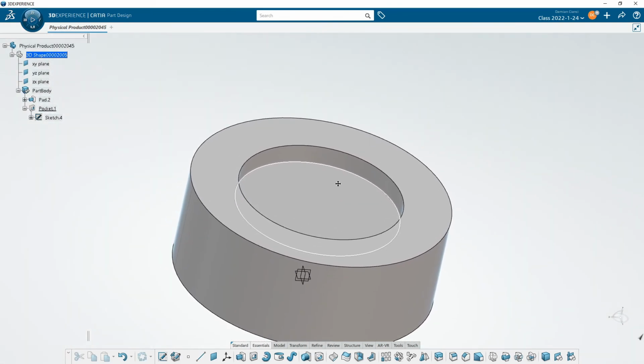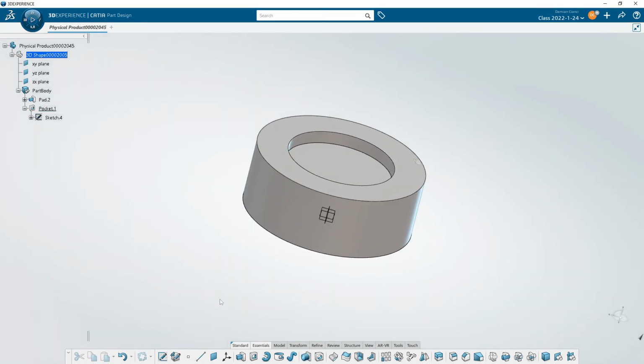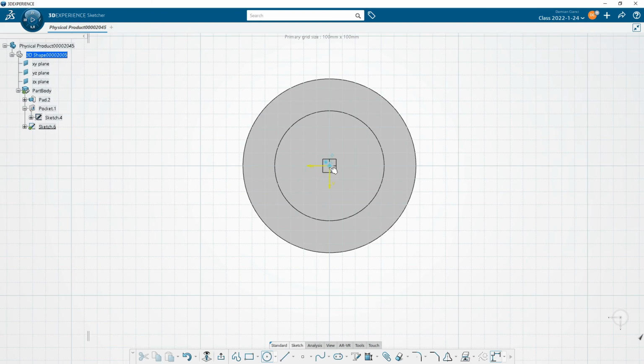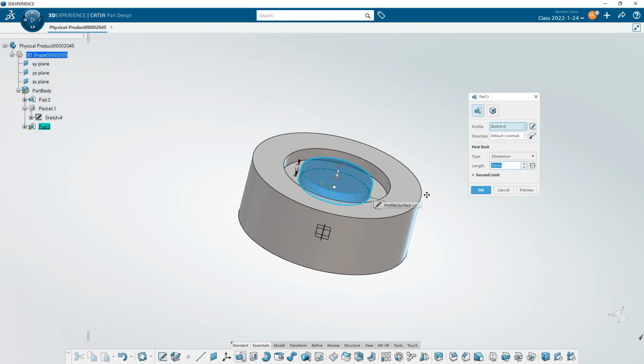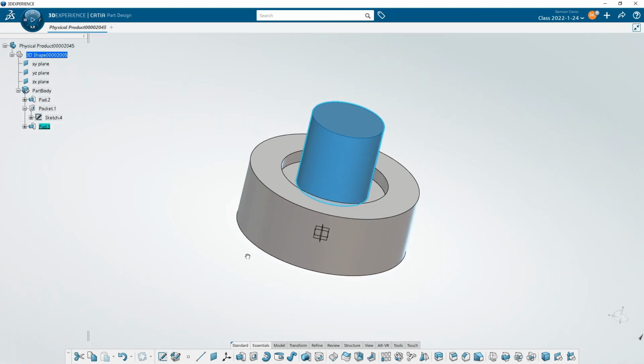This is the basics of CAD, right? We make a solid thing and then we start cutting through it. So then, for example, I could go here and I could hit sketch. So then I go, okay, well, I want another circle. I'm going to snap to the center. I'm going to bring it out like this. I'm going to exit out, and then maybe this time I will pad it up, and maybe I'll pad it up 60. And so I just typed in 60 and hit enter really quick.